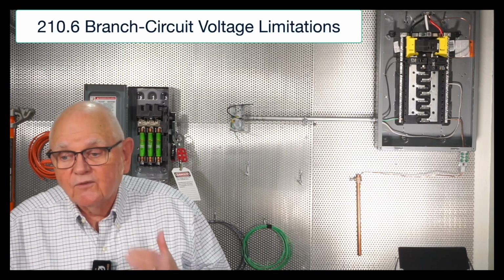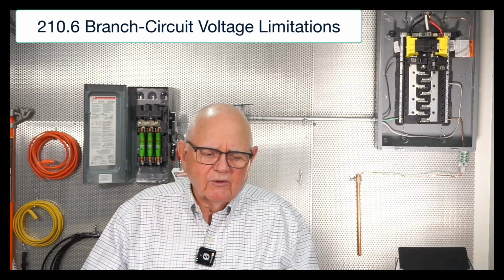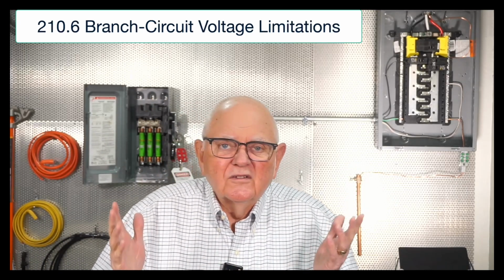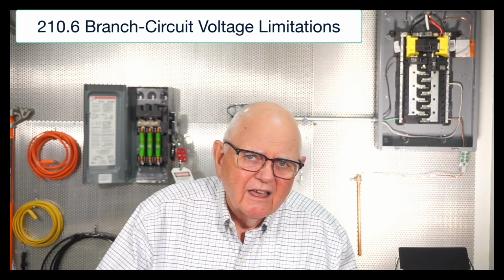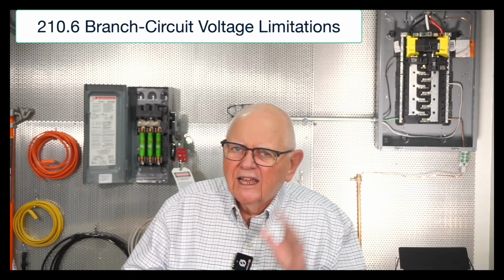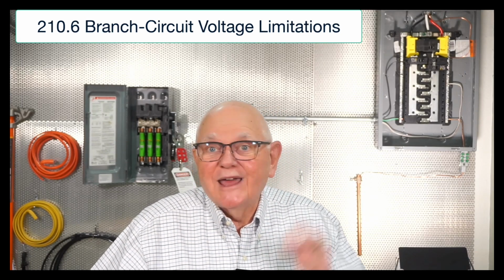210.6 gives us specific voltage limitations, depending upon the occupancy and any specific applications that we have. For example, in a dwelling unit, we're not allowed to use anything above really 120 volts for lighting. I can't have 277 volt lighting in my dwelling unit. I have worked overseas where I've seen 3-phase power and 277 lighting in a very nice home. But anyway, that wouldn't apply here in the United States, would it?